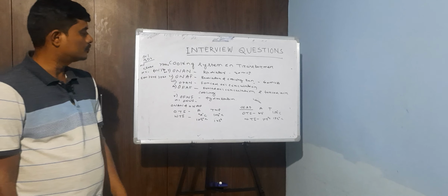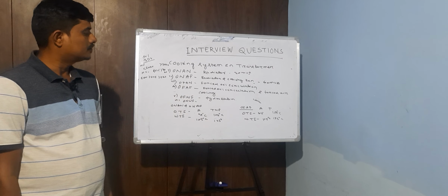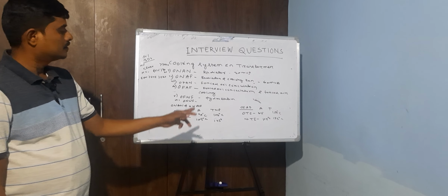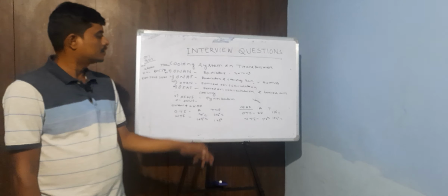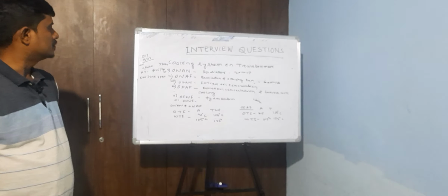When we use OFAF, at that time the OTA alarm setting is 85 degrees centigrade, tripping setting is 100 degrees centigrade. Then WTA alarm setting 105 degrees centigrade, then tripping setting 135 degrees centigrade.